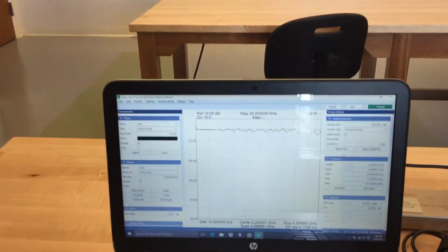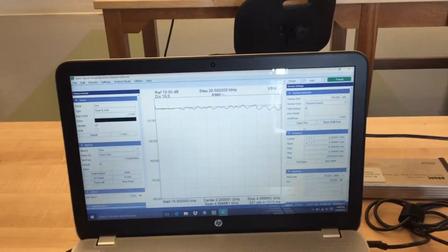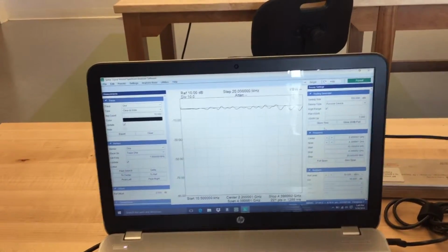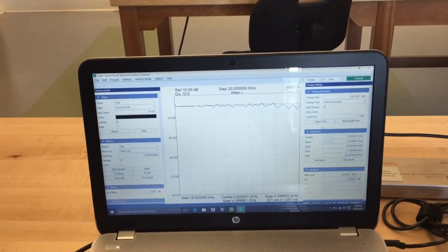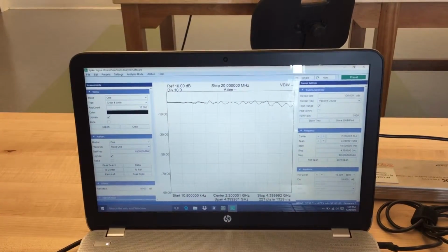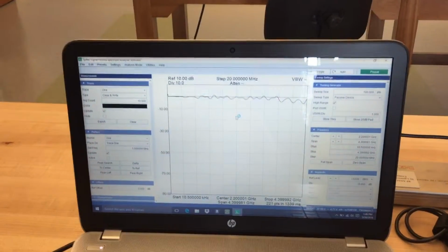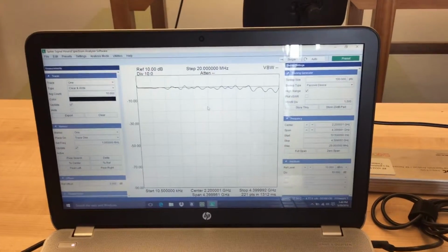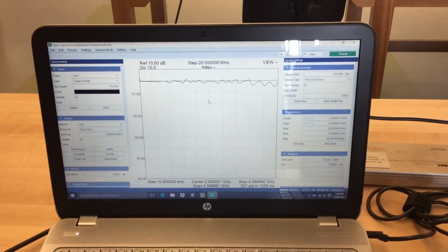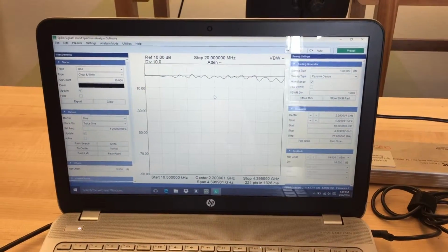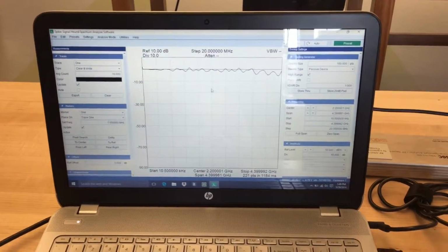And now, do you see what happened? All we did was add a line. And Rob, what do you see here? Describe what you see. The signal dipped down once we added the longer cable. And instead of being flat, we have some oscillation going on. So there's certain frequencies that don't like to be transmitted through this network.